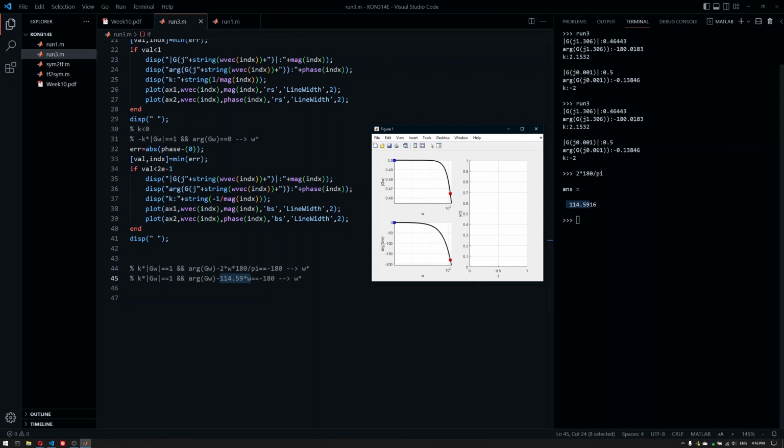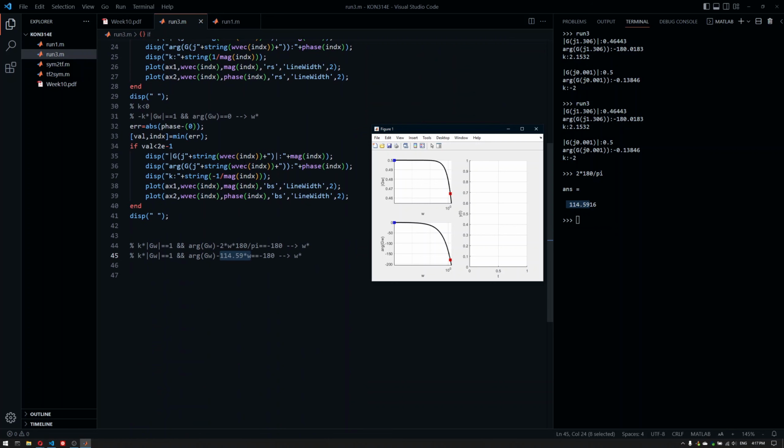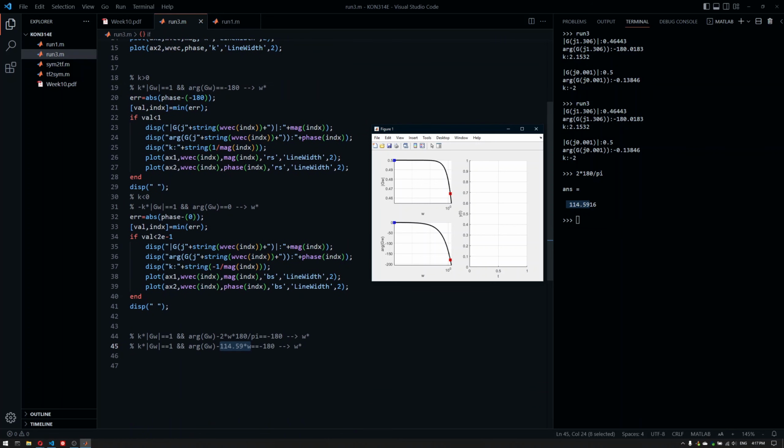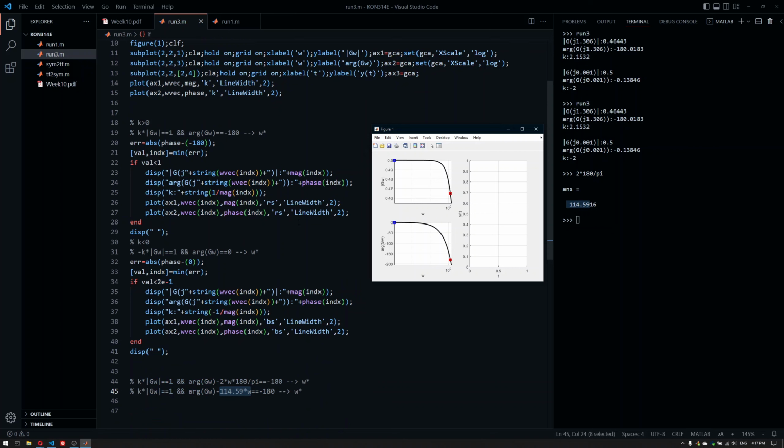We're searching for the phase value, for example, 180 degrees. And if you're using logarithmic scaling, it's almost impossible to hit the target there. So if you're dealing with MATLAB and systems with delay, you might look for linear spacing even, because it might not exceed 1 radian or 10 radians, as is the case for this system. Of course, there's no general rule. You should look at the Bode plot of the system and see what frequency range is the best here. And we can see that we have basically these 2 points.